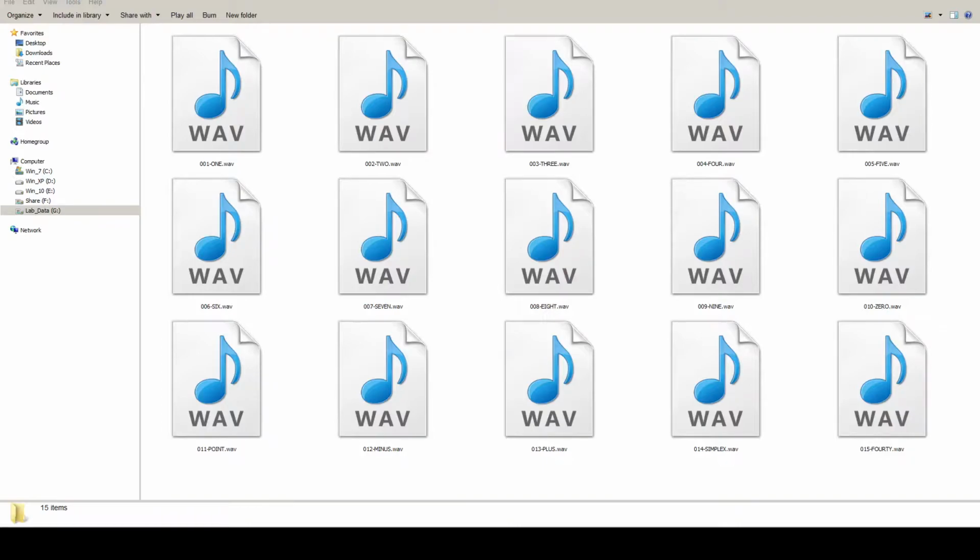These are the wave files I had to create for the speech processor. Each file corresponds to the number that is displayed on a particular segment of the 7950 2-meter radio that I'm using for crossband on the repeater. So in software, I need to decode the segments of the readout and play these files according to what the segment shows in order to read out the frequencies. These are the individual files that have to be chosen each time a segment is read out.